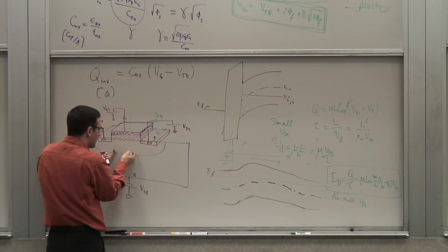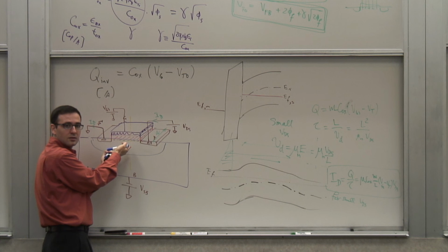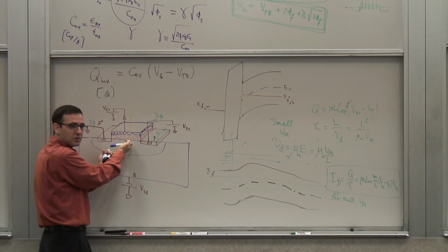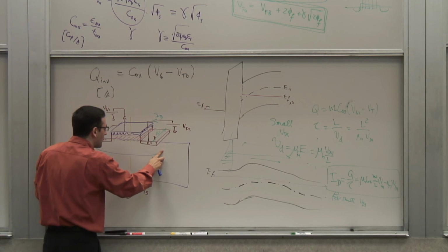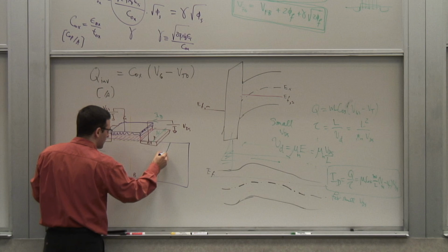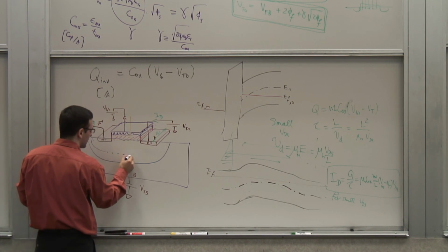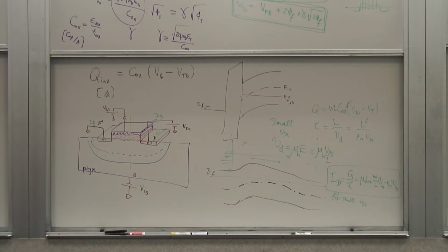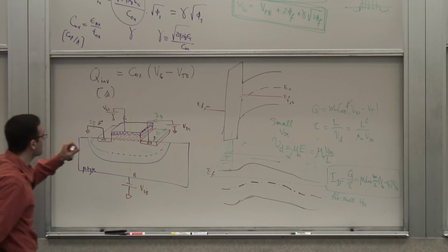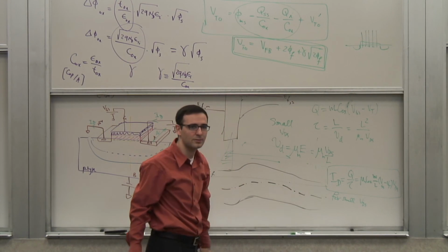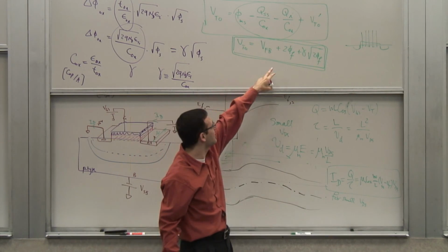So there is a depletion region right underneath this. First we have to form a depletion region, and then we have to get the inversion, right? Now, let's say this is a positive voltage, so it makes the depletion region larger. It extends the width of the depletion region, right? Now, which one of these two terms do you think it will affect? The surface potential, the first one or the second one?